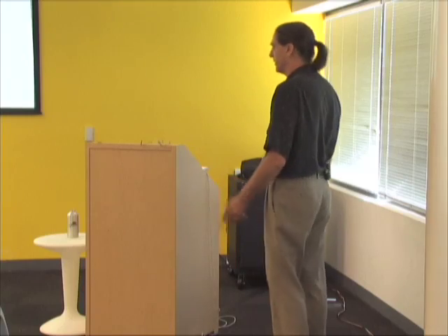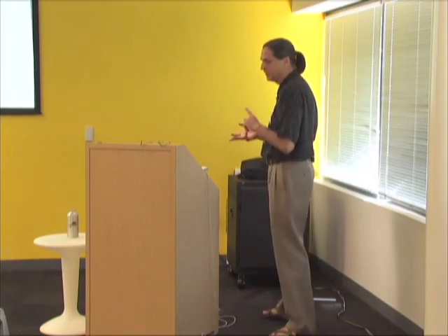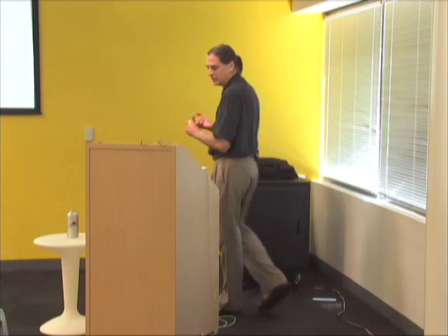Okay, I want to talk about creating visibility controls, and these are all elements in SketchUp which if you use it for more than a few months, you should understand are there. And I'm going to talk about layers, I'm going to talk about using sections, I'm talking about hiding geometry, scenes, the outliner. These are all basic parts of SketchUp.